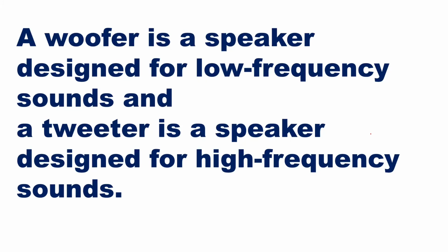Then we'll see what a woofer is. A woofer is a speaker designed for low frequency sounds, and a tweeter is a speaker designed for high frequency sounds. For low frequency, you require a bigger diameter diaphragm, which is loosely connected, so that for any input of low frequency it can vibrate.